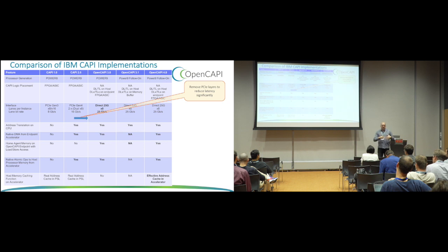We moved nearly all of that logic onto the processor chip for this next version. So if you look at the way we're doing caching in 4.0, it was definitely learning from the way we did it in these previous generations, to enable a more efficient caching solution. But it's all 25 gig, right? We got 25 gig signaling, and essentially we'll have 16 connectors for memory.